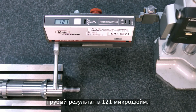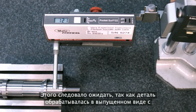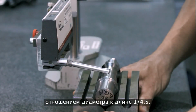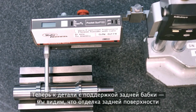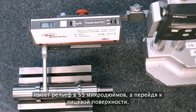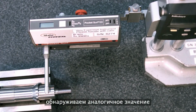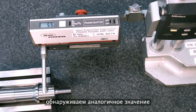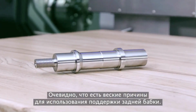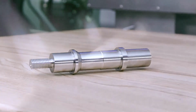This should be expected since this feature is cut hanging out at a 4.5:1 length to diameter ratio. Moving on to the tailstock supported part, the rear journal has a finish of 55 micro-inches, and moving forward to the front journal, we find an equal value of 55 micro-inches. It's easy to see there are great reasons for using tailstock support.